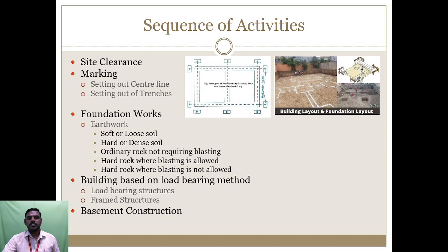RCC means reinforced cement concrete: the reinforcement is provided for taking the tension load, and the concrete for resisting the compression load. So both compression and tension are carried by the RCC material. So the lintel, constructed in between the brick walls, will carry the load below the opening surface.